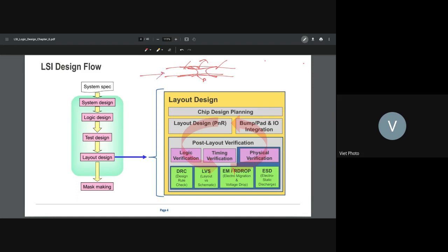So the way the EM works here is it will calculate the current through here, and they calculate the width here. With this width, they will allow only a certain max, I max, actually I average max, so that over, let's say, the life of 10 years or 20 years, this one is still okay to conduct well even with the electromigration.